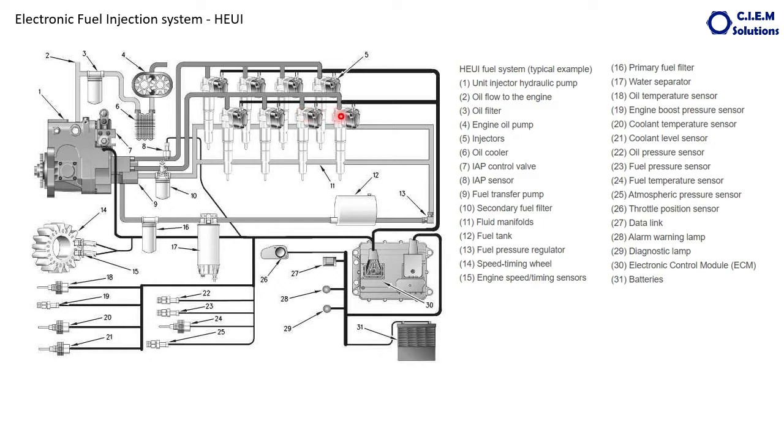If the fuel is not injected, it returns to the tank, from both the banks. This is called the fuel circuit. This circuit only helps to keep the fuel readily available at all injectors at the desired pressure. There is a pressure regulating valve in the return line.